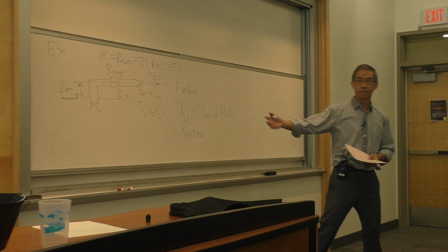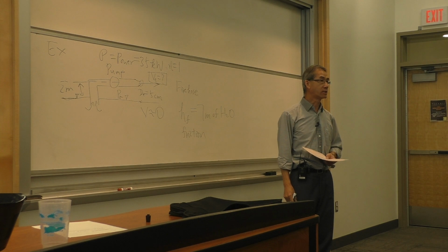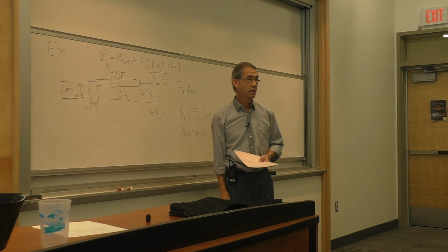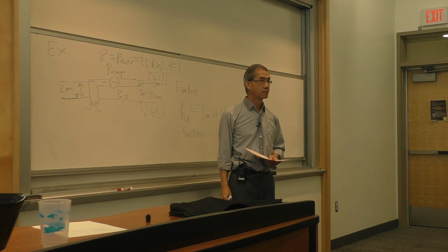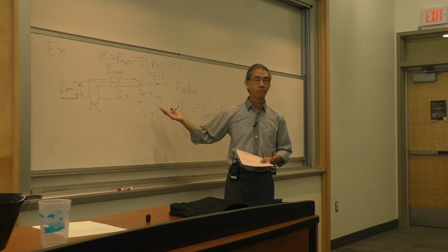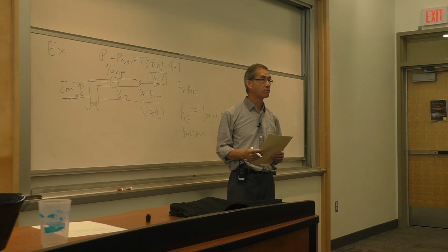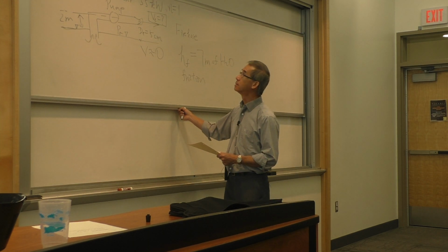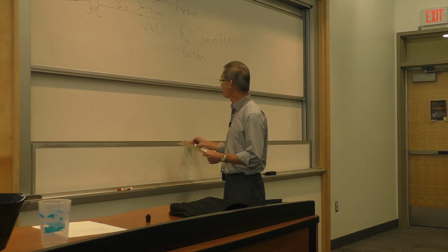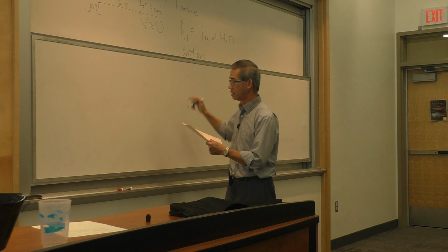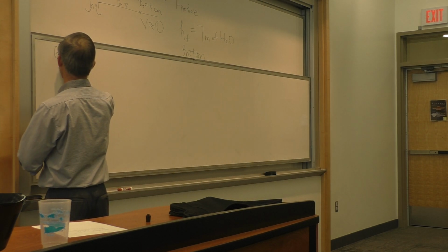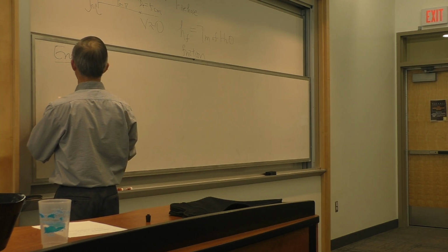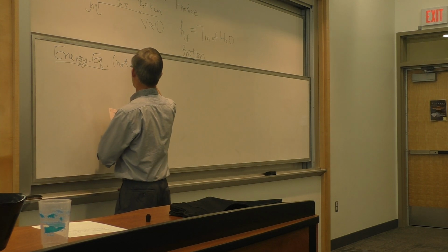I have to pay a pump at 35 kilowatts to overcome the friction effect, the change in elevation, and the change in kinetic energy. And when I do all of that, it turns out this problem by way of the energy equation is solvable. It's very doable, and that's what we'll do next. So the energy equation is given in a form that's very dangerous because it resembles the Bernoulli equation. So the energy equation, and I'll emphasize, not Bernoulli.